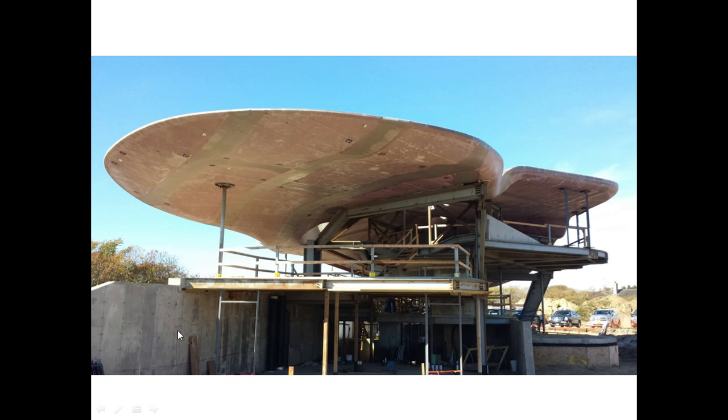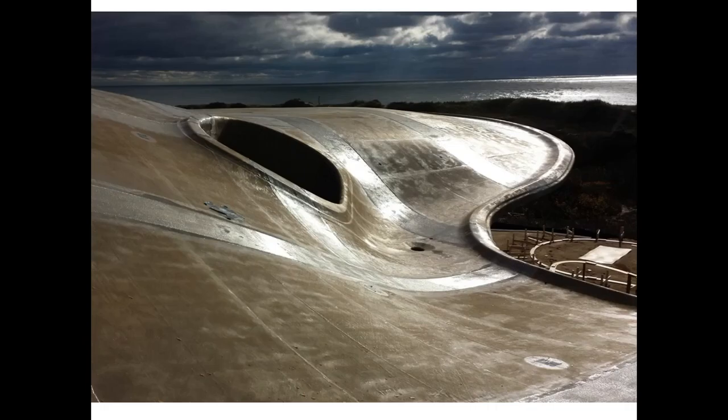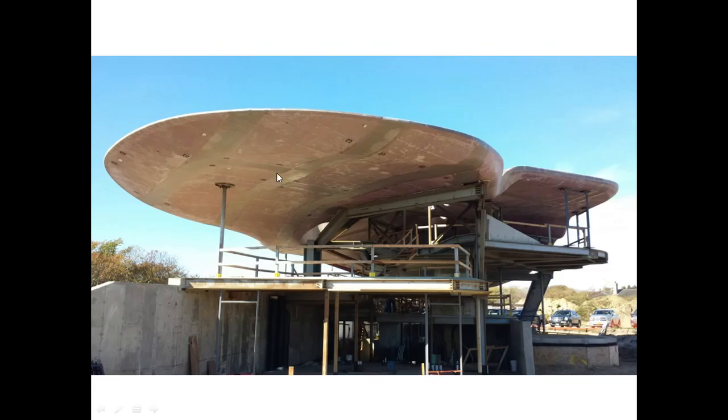It's pretty much uniformly cantilevering. You can see there's a little steel portal frame here. Some other quite nice things going on actually. Quite like this canted concrete. Concrete goes to steel. Steel goes to fibre reinforced plastic, which I think is really rather elegant. So there's the flying surfboard. Of course, one of the things you have to do with such a lightweight roof, and of course it is incredibly light, is this post here is not only supporting most of that cantilever, but it's also tying it down, because of course if you open windows here and any wind does get inside, it's going to want to take off.